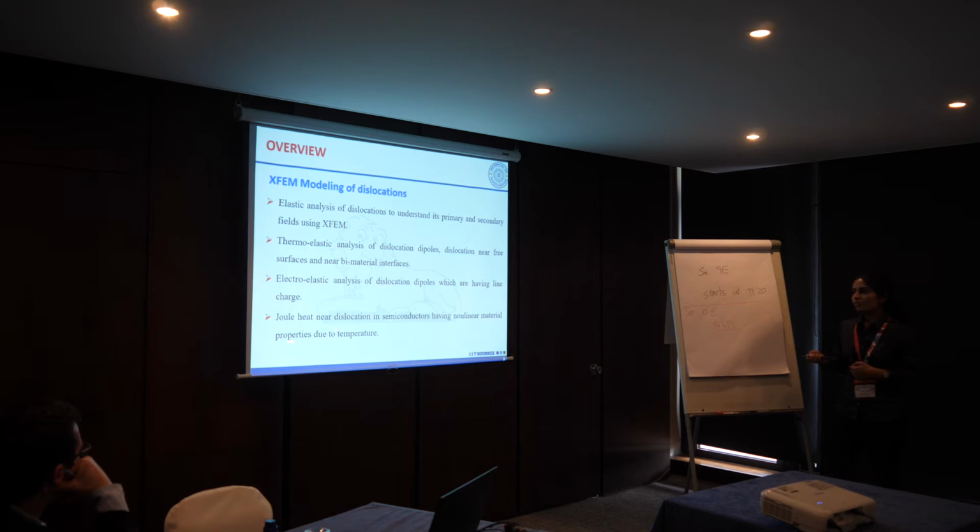Other than that, electroelastic modeling of dipoles has also been done. Since we are considering semiconductor materials, they have an electric field around the dislocation core, which will generate heat. So that Joule heat will be considered near the dislocation core.